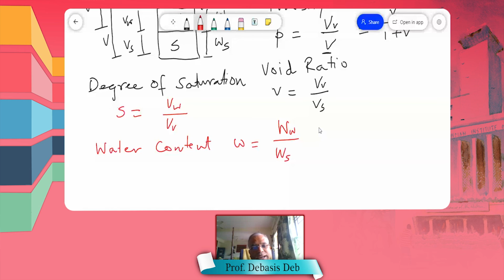Okay, that's the weight with water. Then we put that sample in the oven and dry it so that the water goes away. Then we take the weight again, so we get the dry weight. That becomes our WS. And the previous weight we have taken is W water plus WS.